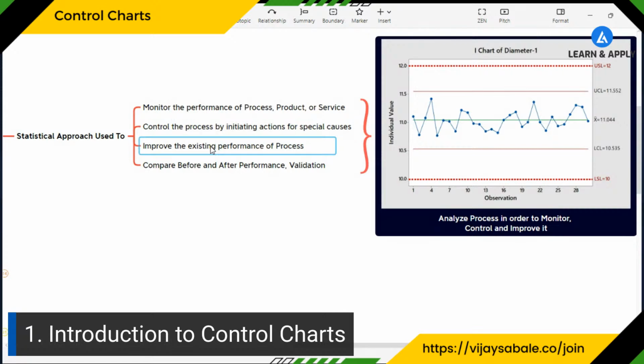The third application is that we can improve the existing performance of the process. So if you want to improve the existing process, we also need control charts. Now, if I want to summarize that, if you see this magical triangle, monitor, control, and improve, for all these three important actions, we need a control chart. This control chart can also be used for before and after comparison. That means, let's say you have improved the process, you have taken some actions, and now we want to check whether the performance of our process has improved or not. That can also be checked with the help of before and after control charts. In other words, we can also use the control chart for validation.